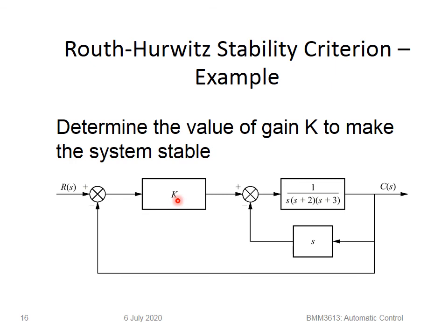But there are dangers in choosing the value of k. What we're afraid of is that there might be a certain value in this system. For example, just now we've seen that if k exceeds the value of 1386, then the system will become unstable. So this is the case where we use the Routh-Hurwitz criteria table. So let's take this example.